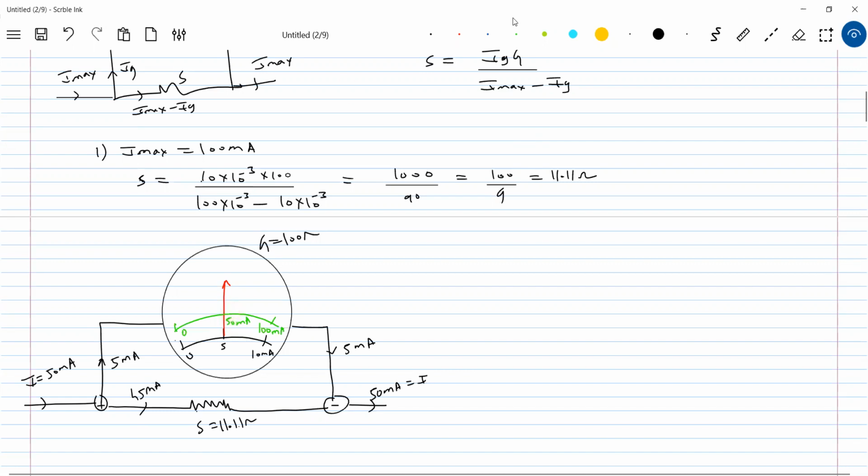So there are two scales. This will be the ammeter scale. Now which scale should we look at? The ammeter scale. Therefore, in the lab, I close the galvanometer scale. If I close that, only the ammeter scale will be visible. If I send 50 milliampere, the pointer will be at 50 milliampere. If I send 10 milliampere, it is a similar diagram.